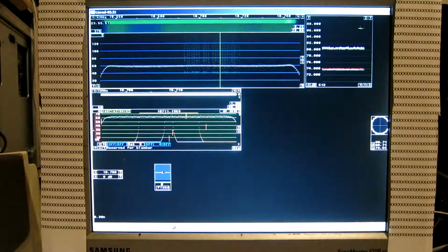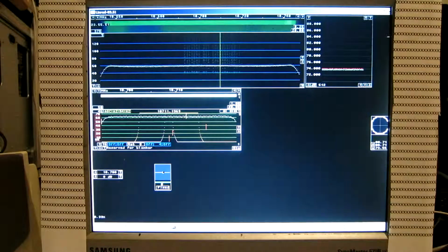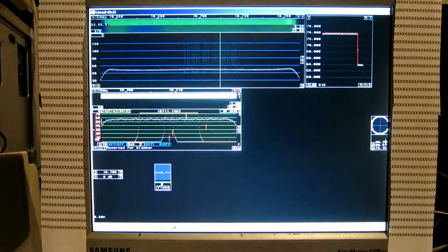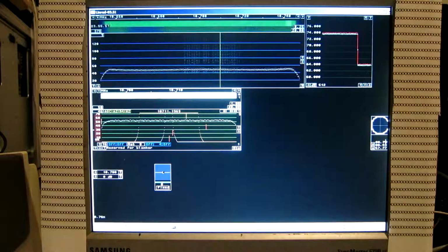And I want to look at the RMS power here. Now I introduce 10 dB attenuation. And it looks like we got 10 dB less signal. So for that reason it should be safe. We are well below where anything saturates.